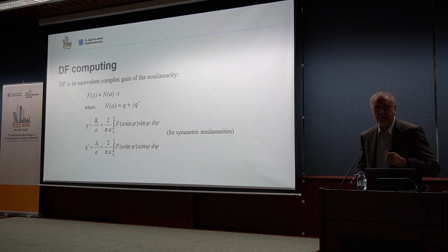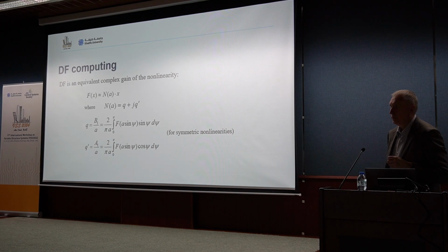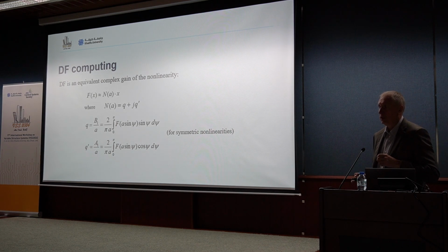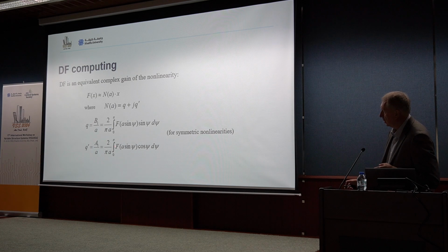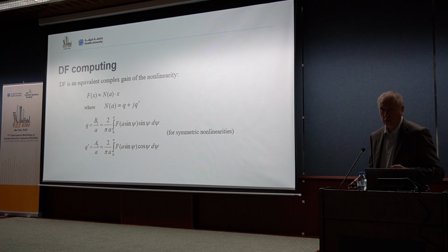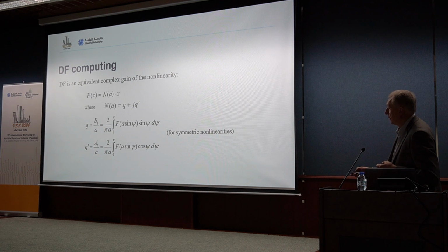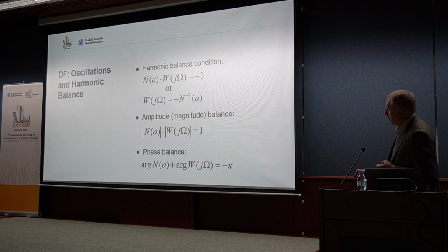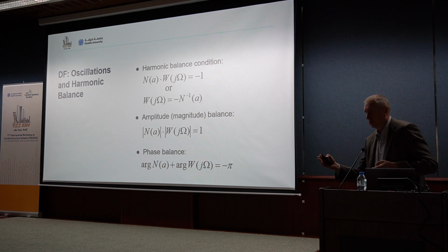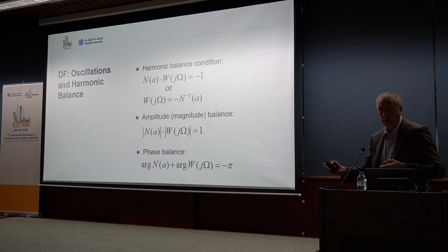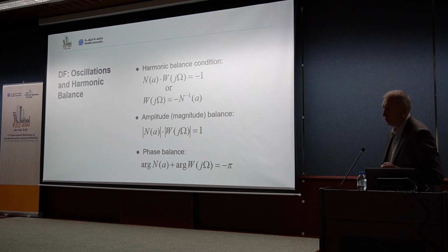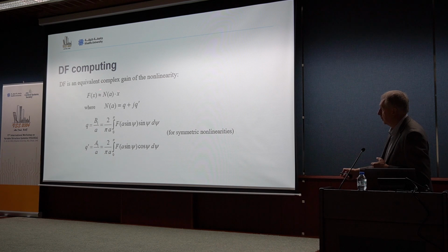However, if the nonlinearity is a single-valued, odd symmetric nonlinearity, then we can easily prove that q prime, which is the imaginary part, is zero, and we have only the real quantity in this case. And easily from this property of the closing loop, we will find, if we replace our nonlinearity with this